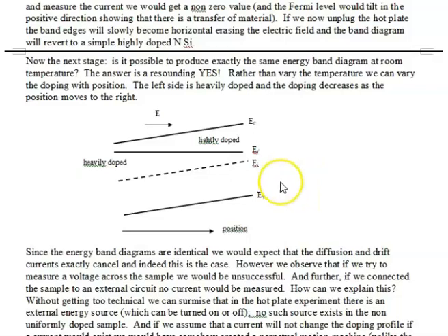So non-uniform base doping gives an electric field, which gives an electric push, which gives a healthy drift component to charges which find themselves in the base, and that gives an increase in the current and an increase in the device performance.